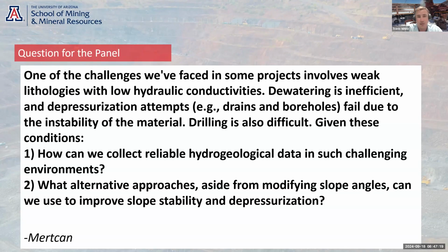The other way around it, if you aren't able to install casing, and this is Simon's bread and butter, is installing VWPs through the drill string. So as you retract the drill string, you can put your VWPs in grout on the way out.